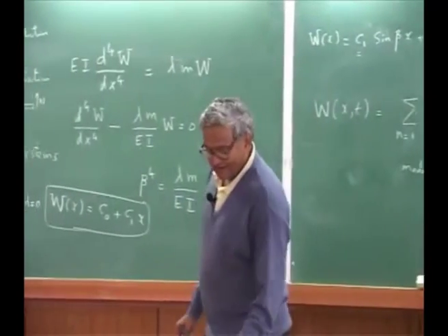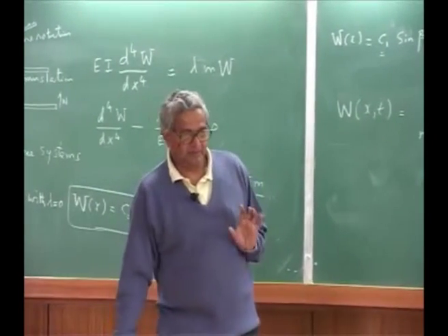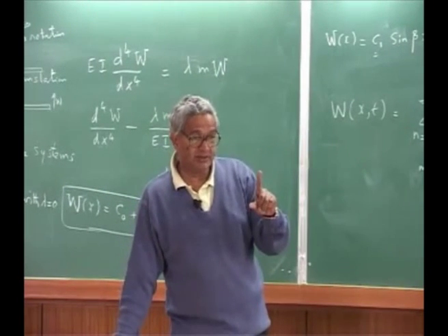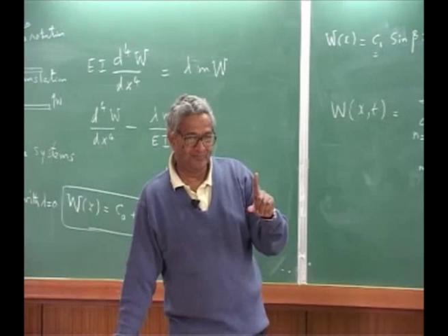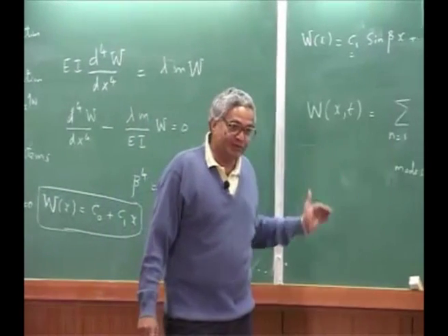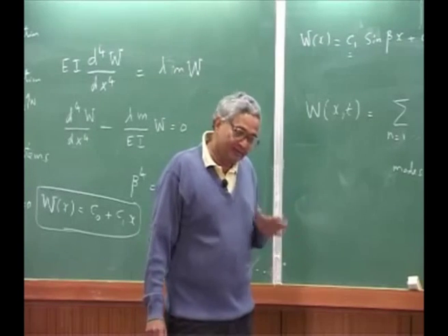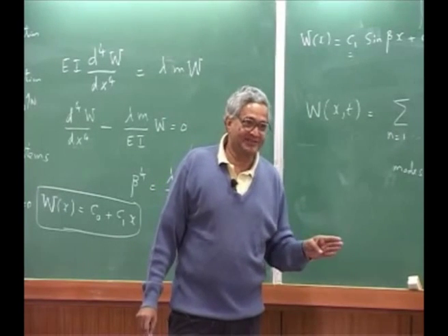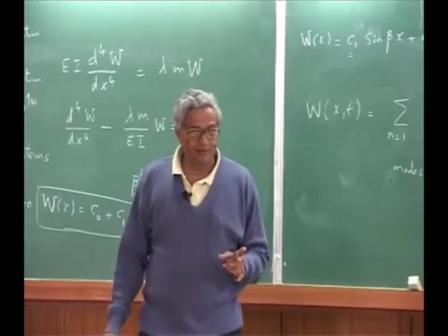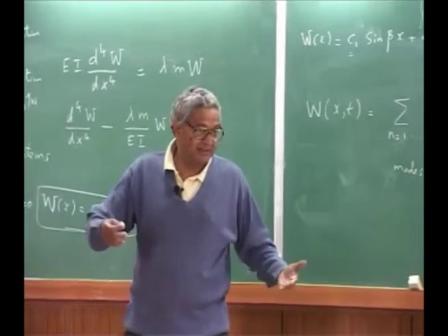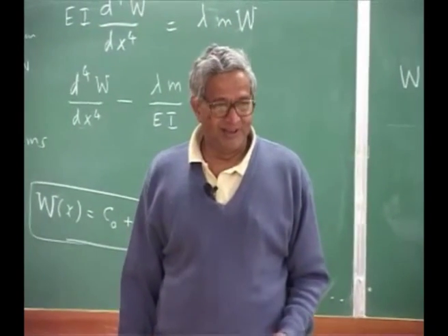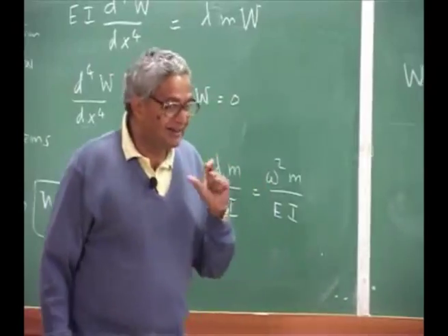Well, it's a little tricky. It should reach that value, but you will still have a rigid body mode. Please understand, because what will happen is the flexible modes will be tending towards that value, but you still have the rigid body mode which you cannot remove, because I have a heavy mass. That doesn't mean it is fixed, all can move up and down.